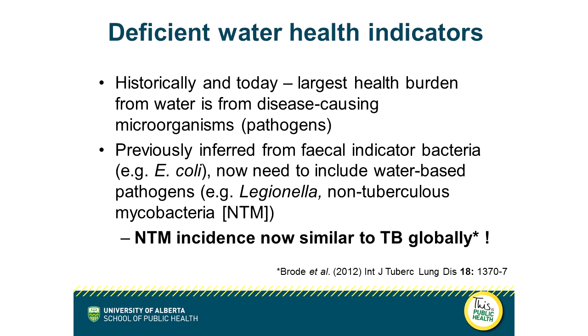So to talk about some of the deficiencies now, so you've heard that waterborne disease was a major problem. Measuring pathogens is a very expensive and time-consuming proposition. So we've relied on what we call fecal indicator organisms to tell us whether or not we might have fecal contamination in water. And the assumption is that some of that may be from humans if we're in an urbanized environment. And we've used this organism E. coli from the early days.